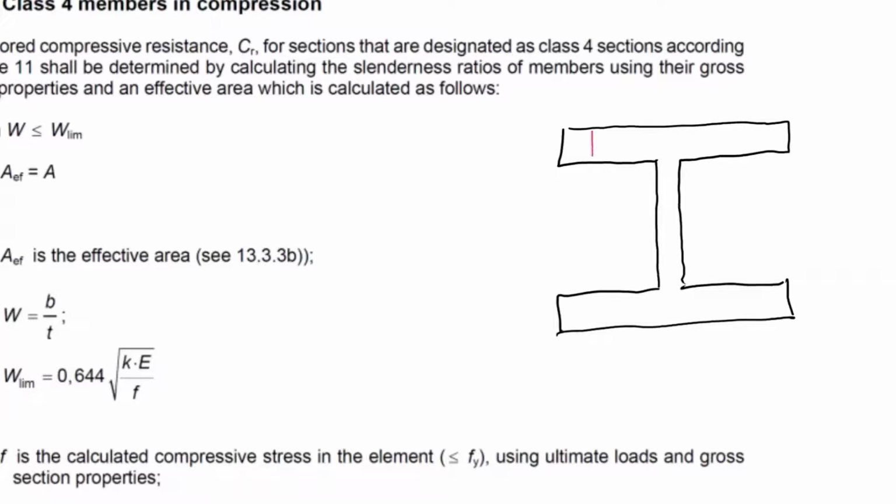And to account for that, to make my life easier, what I'm going to do is just remove some cross-sectional area. Actually, let me draw this in a different way, and then you can see that you can apply this in different ways. I'm going to draw a horribly asymmetric section, and what we will do is classify this section, find, oops, it's class 4.